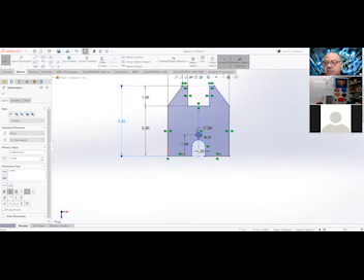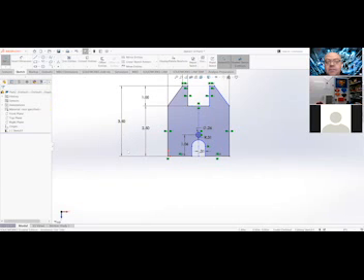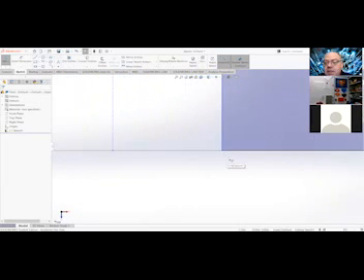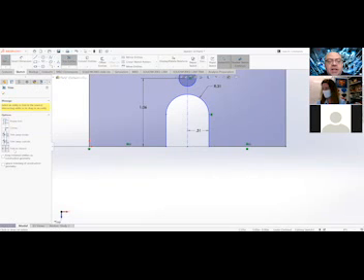So I trimmed out these lines inside this archway. I just used the trim entities, and I selected the 2 lines that were there. But the dimension makes it look like there's still a line there, which you get used to. You'll notice the thickness of the line. That dimension line is relatively thick compared to the object line. Remember we did our line weights in AutoCAD? This is part of seeing that, so that you can recognize the difference. I just used trim entities, used trim to closest, snipped, and took those out. Does that answer the question?